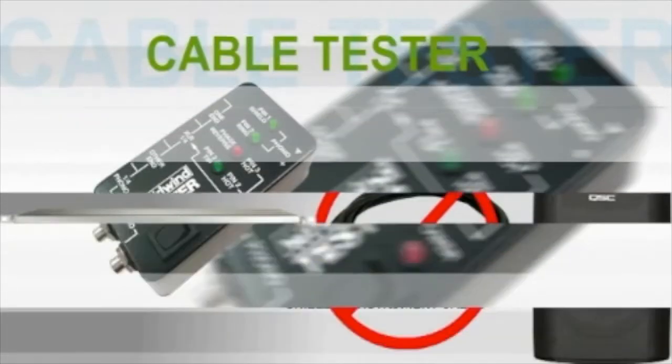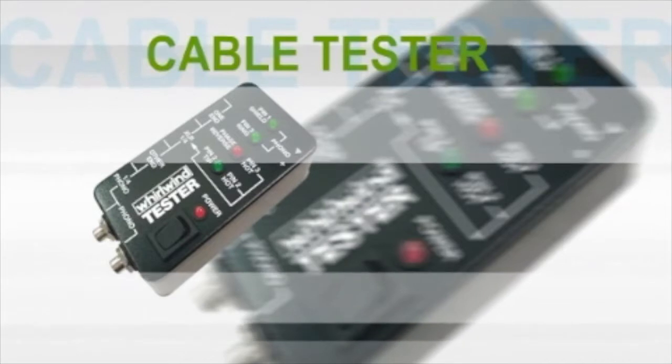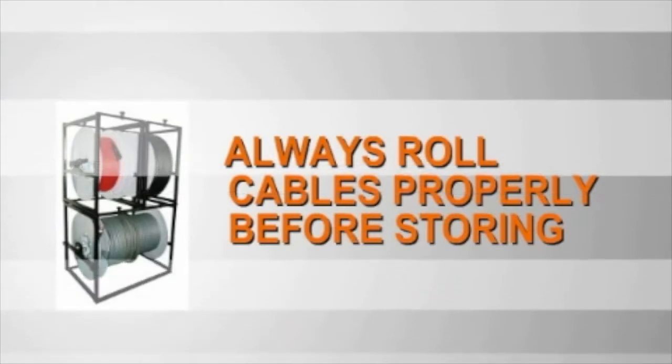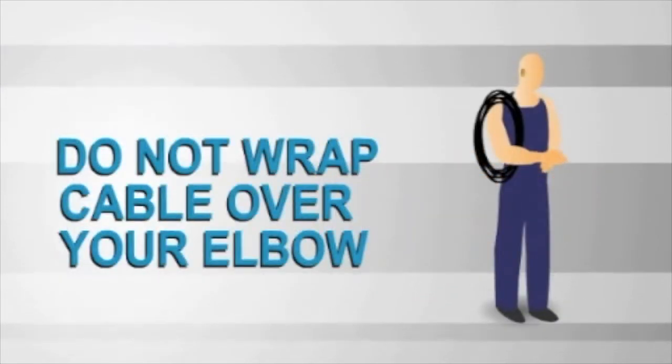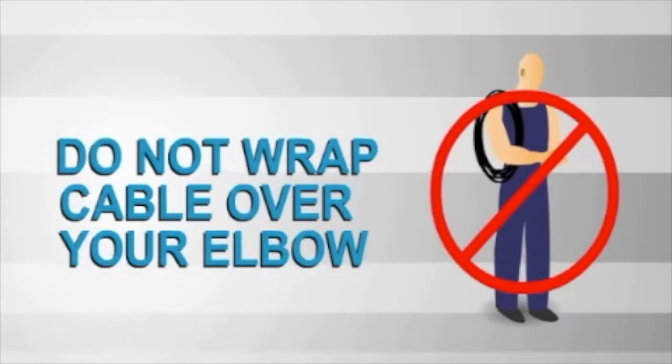Check all cables with a cable tester before energizing. This basic procedure will rule out simple issues and possible problems. Always roll cables properly before storing. Do not wrap cable over your elbow, as this can cause damage to the cable and extreme frustration.